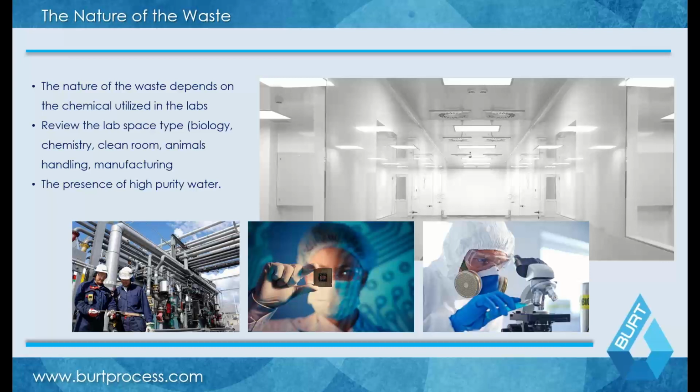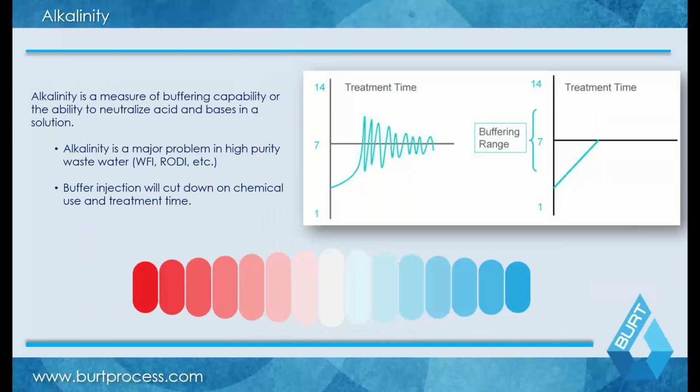The other thing is the presence of high purity water, or alkalinity implications, when it comes to a pH treatment system. And alkalinity is one of those things which is a little bit hard to understand. Anybody who works in the realm of high purity water knows that when you're making high purity water, whether it's WFI water, RODI water, or ultra pure water, the processes you're going through, RO and deionization, take all the mineral content, or the majority of it, out of your water.